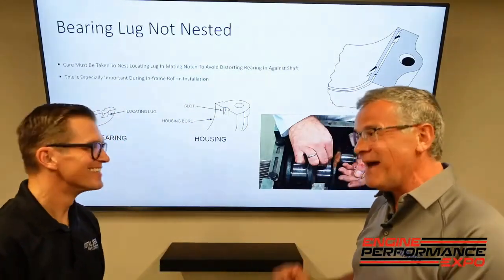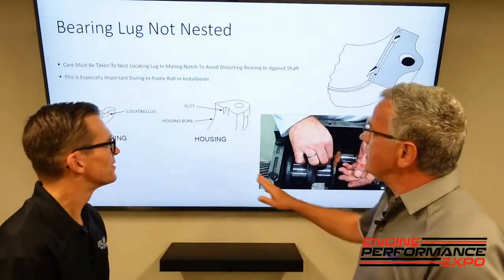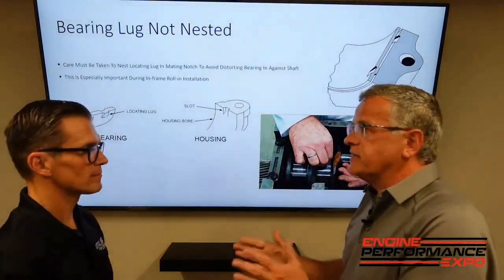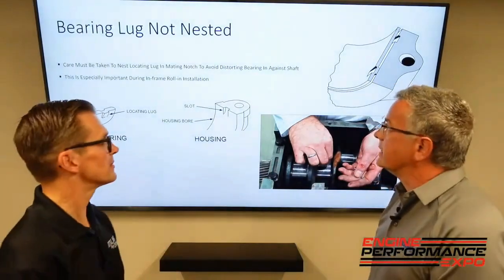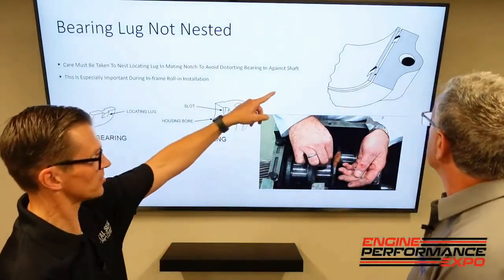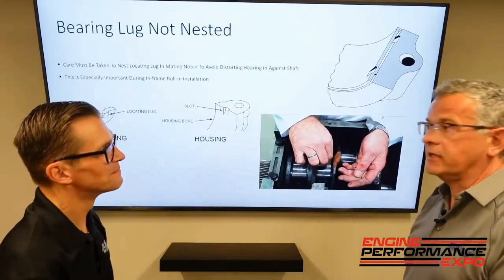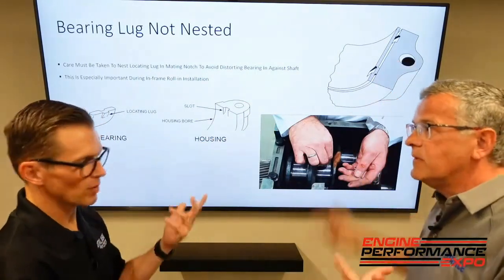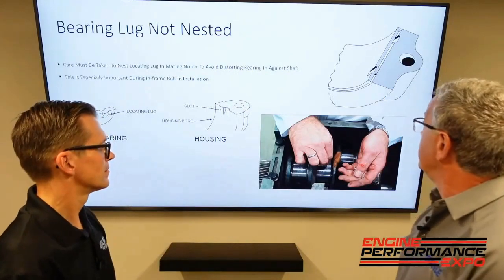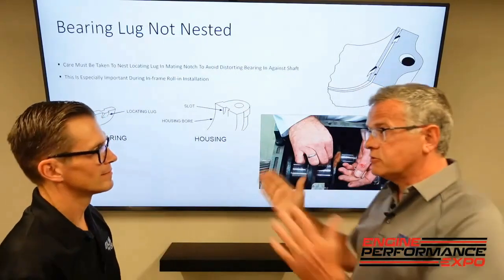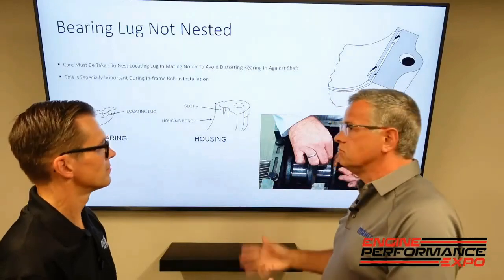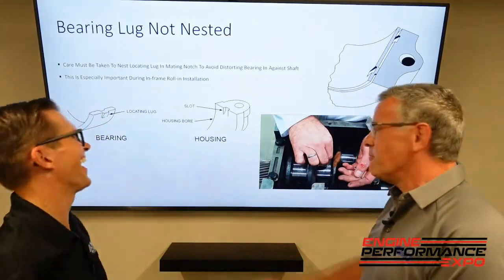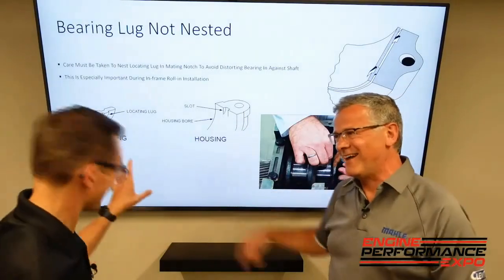Now, there's other issues that can happen with that, but the locating lug is simply just to put it in its right nesting spot. Locates it. Exactly. The name's it. So it needs to go where it's supposed to go, not where it doesn't. Exactly. So in some cases, he probably has an upper and a lower mixed up. Right. And it doesn't fit. And again, if you would put this together, it's going to squeeze together, lose the oil film. I would think you would feel it beforehand, but you never can tell. This is true. Remember, that was on one of the topics.